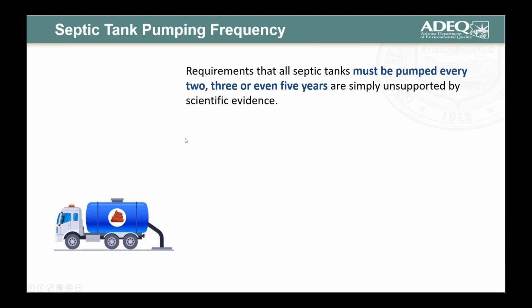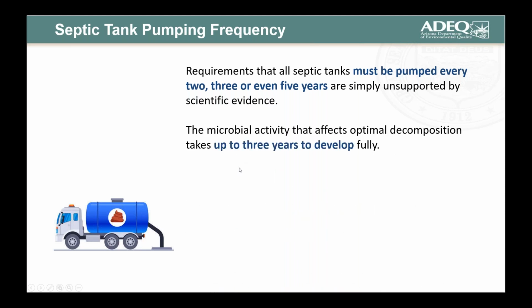A true septic tank that's in front of whatever secondary treatment device should be properly sized. But if we have only a septic tank with proper sizing of 2.1 days detention time, you can pay attention in particular to what I'm saying. The microbial activity that affects optimal decomposition takes up to 3 years to develop fully. So if you pump it every 2 or 3 years, you're never even really getting optimal microbial development.